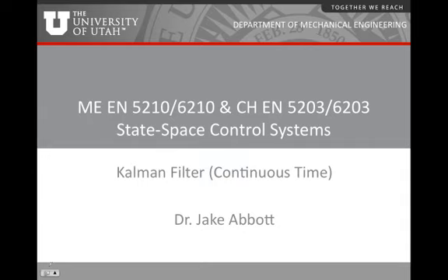It's analogous to the LQR controller, which we've seen previously. The LQR controller, the linear quadratic regulator, was a way to choose our controller gains that went beyond just simply placing the eigenvalues of our system somewhere. It tied the choice of the controller gains more closely to the actual system performance.